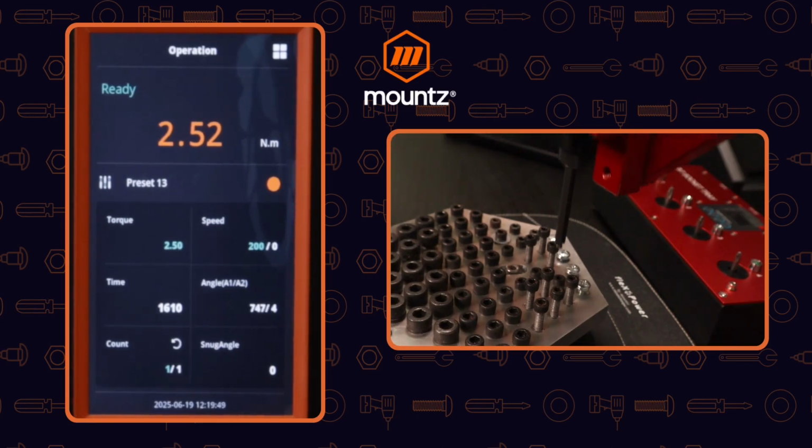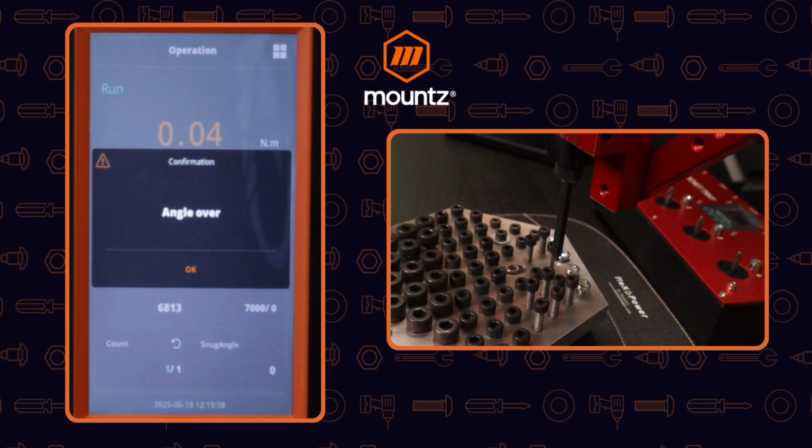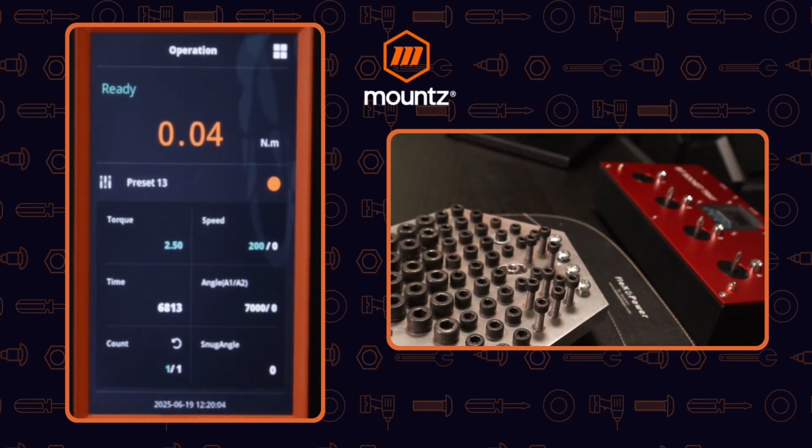Now, if I were to simulate the actual stripping fastener, if we run the fastener again more than 7,000 degrees of rotation, we'll get an angle over error here. And so we are again helping to error proof this assembly process for this fastening, to alert the operator to go ahead and correct that mistake right now before it becomes an issue down the line.